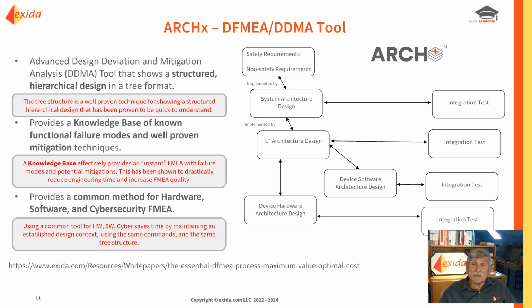REQx is the architecture design verification tool that's part of OEMx. That's a tool that uses the well-proven design failure mode and effect analysis, except it's been modified so that functional safety requirements replace some of the old DFMEA requirements, and new design documentation information is added. We call that method DDMA, Design Deviation and Mitigation Analysis.